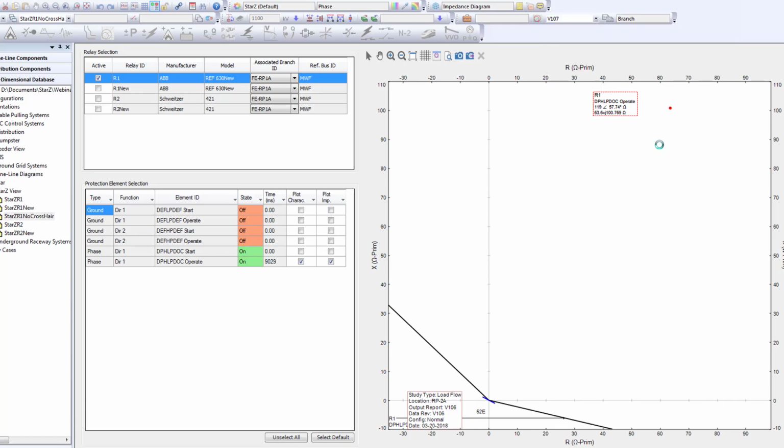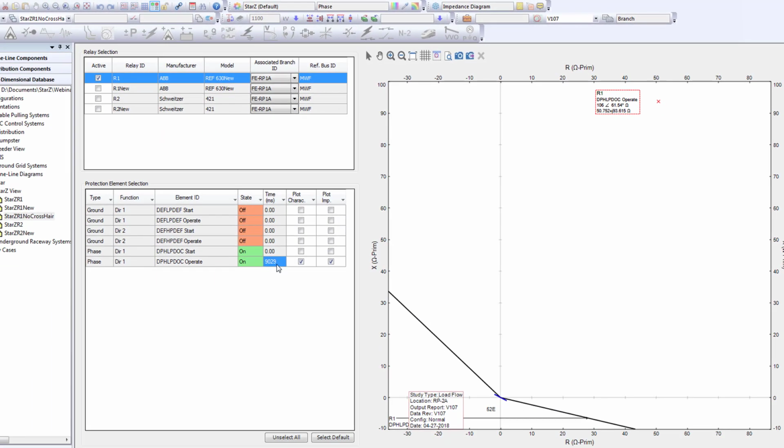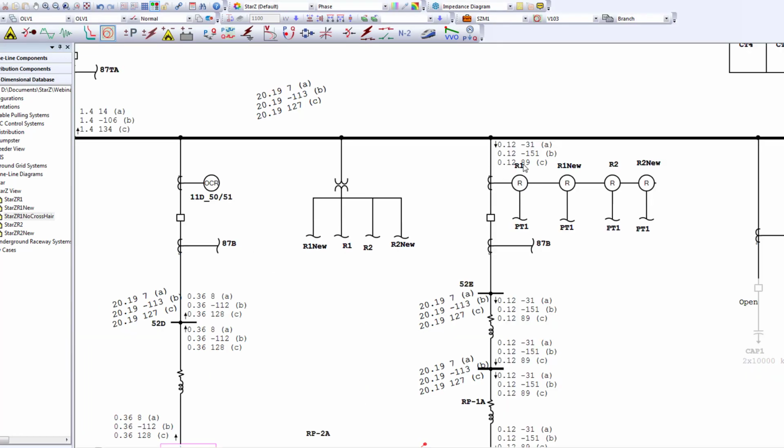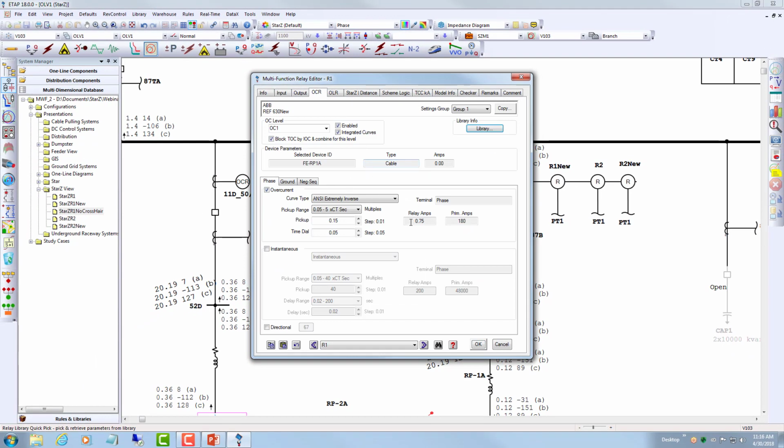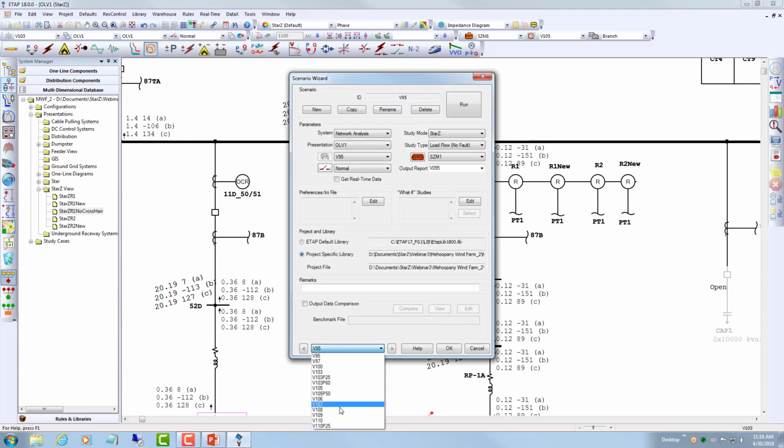Now if I go to 7%, you see that the relay actually trips at 7% overvoltage, and you can see the trip time of the relay, which is 9 seconds and 29. From the OLV also, what you can do is look at the current. For the overcurrent relay, the pickup value is set to 180 amperes. So if we go to 105, in this case, I need to run 105 to look at the current. So what I can do is go here and run the 105.